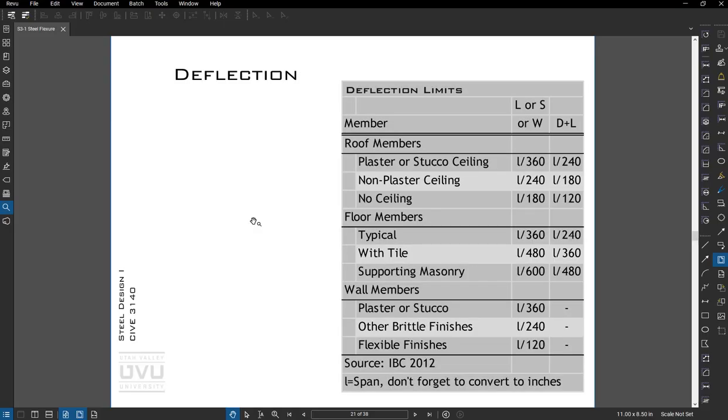All right, deflection limits. Here are some criteria from the IBC. This is a good place to start. Talking to the owner and understanding the building use may change these. For equipment, usually we're in the L over 400 plus. Definitely check with the manufacturer as to what they require. Sometimes they'll give you a number, sometimes they'll look at you like you're crazy.